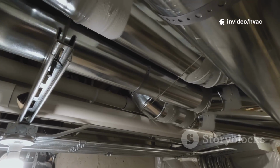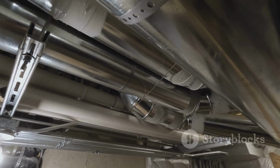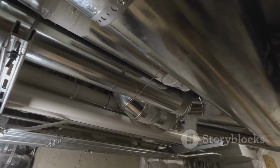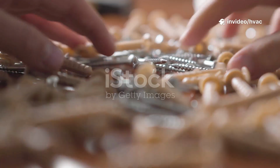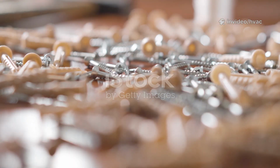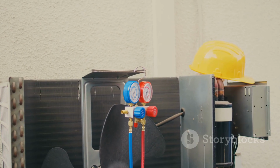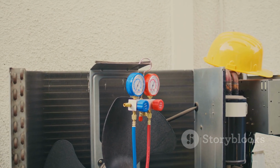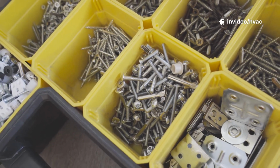When selecting capillary clips, choose a material that resists corrosion. Stainless steel is a popular choice for durability and longevity, especially in humid or corrosive environments. Make sure the clip material is compatible with both the sensor and the coil frame to prevent galvanic corrosion. Before you start, calculate the number of clips required for each coil. As a rule of thumb, use 1 clip at each end of every sensor pass, and additional clips every 18 to 24 inches along the length.